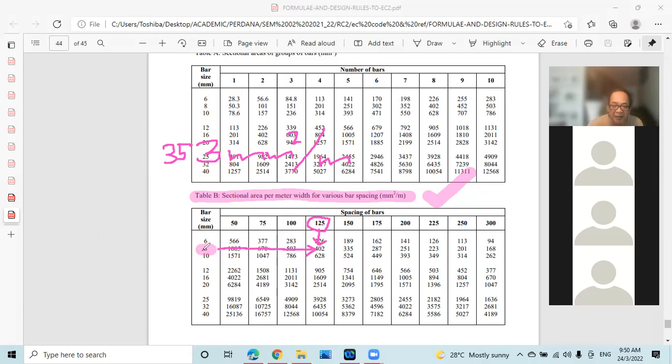So this is how we come up with the reinforcement. Looking at the diameter, we have our calculated AS required, and 402 is the AS provided. Okay. H8 at 125 is the area provided. It gives an area of 402 millimeter squared for every 1 meter width of the staircase. Right? We can even choose to have a different one. Let's say I want to choose, I use a different color, 10 mm. Can also. Okay. If I use 10 mm, then my spacing would be somewhere here.